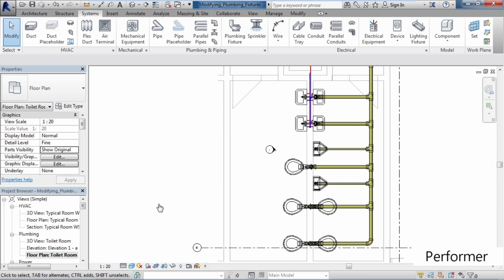But we also have waste lines, removing the water and waste from each of the actual water closets that are shown in my actual model. Those waste lines belong to a plumbing system. So before we start to add a lot of detail to a new model, we want to make sure we define our systems. In this case, we would add a plumbing system. Now, the importance of a plumbing system is that it's the glue that holds all of these elements together within that plumbing system.